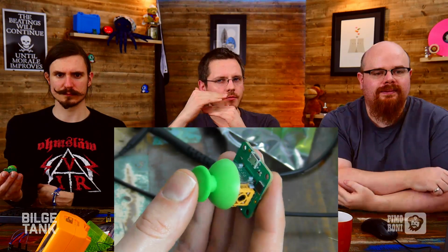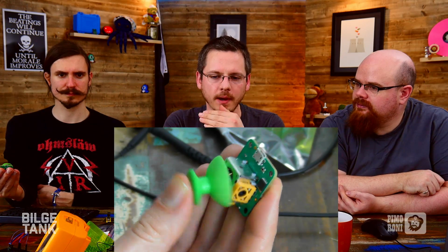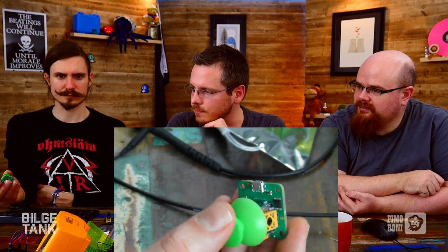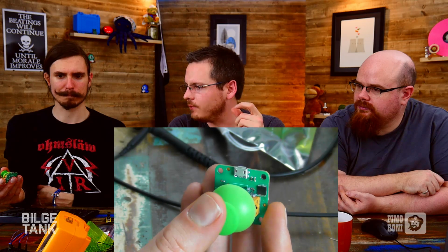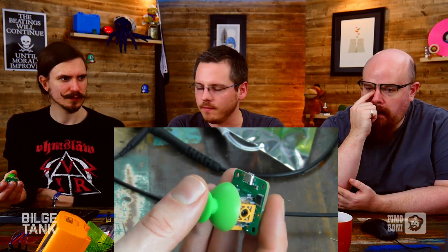One of the caveats of an ADC is that because it splits into discrete levels, if you're right on the threshold of a discrete level, very, very small fluctuations in the input signal can cause you to jump backwards and forwards between those discrete values. With something like the joystick, that means you'll end up getting a reading like 90, 91, 90, 91, 90, 91. So we do a little bit of averaging over a period of time.